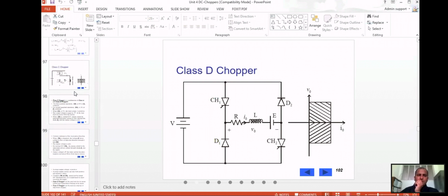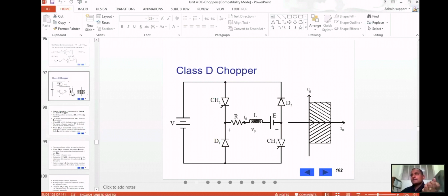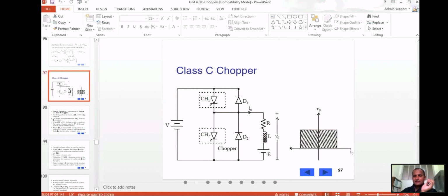Yes. In the case of a rectifier, you're converting AC into DC, right? You do not get a pure DC at the output; you get pulsating DC, so the pulsating waves will be there. To remove this unwanted AC, the unwanted signal, we use a capacitor. Yes, sir.